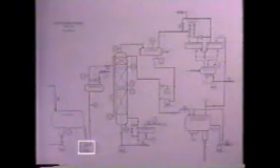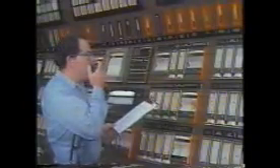Since the outside operator has readied a feed tank pump, the inside operator needs to make sure that there's a sufficient level of mixture in the feed tank. If there isn't enough mixture, the tank could run dry during the distillation process. To check the level in the tank, the inside operator looks at the level indicator on the control board. If the level is low, he'll have the outside operator add more feed mixture.